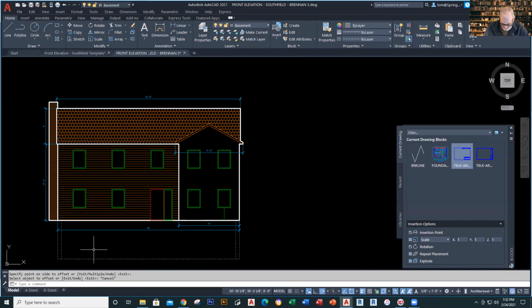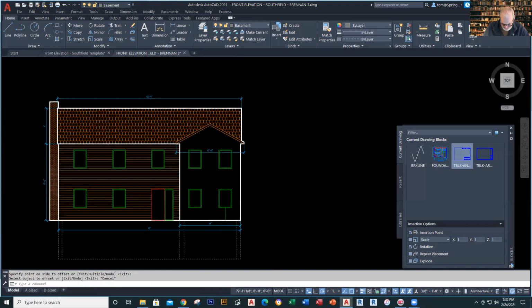Very good. The next thing I would do is I would go ahead and draw this one down right from here. Using my line command, go ahead and go right down here. And you go right down like that. I'm going to offset that 12. All right, so we're going to offset this one to the right, 12. So I got that right there. So this is how we go ahead and begin to put this together.